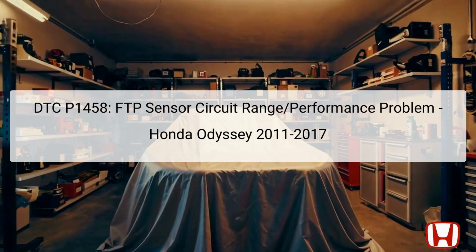The FTP sensor plays a critical role in monitoring the fuel tank pressure, ensuring that the fuel system operates efficiently while minimizing emissions. Located on or near the fuel tank, this sensor sends data to the Engine Control Module, ECM, which utilizes this information for optimal engine performance. Issues with this sensor can affect not only the vehicle's performance, but also fuel efficiency and emissions compliance. Diagnosing this error requires specific tools and procedures, which I will detail in the following slides.